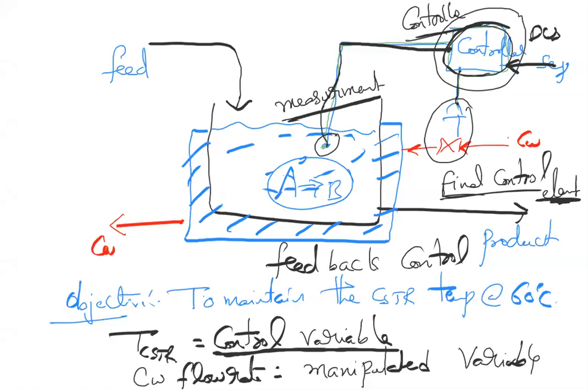That is why all these DCS channels that you call in the plant will have an input output count. So some DCS panels are called, let's say, 1000 input, 1000 output. That means you can connect 1000 inputs from the plant, and 1000 outputs you can take out to the plant. So what are the inputs? They are nothing but the signals which are coming from the plant. So you are taking a lot of information from the plant.